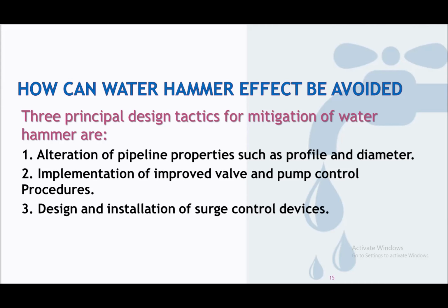So as much as possible, we can avoid having a high point in our profile. And of course, increasing the diameter, we're reducing the value of the wave celerity. Actually, increasing the diameter will reduce the value of wave celerity, but that until a certain value, okay?